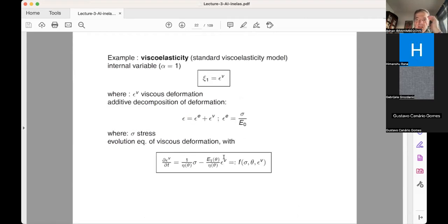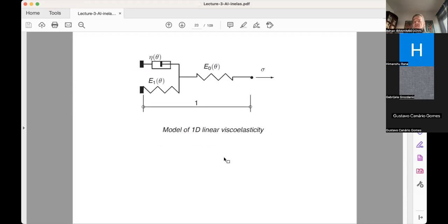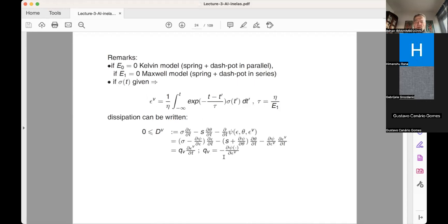We started studying that by looking into so-called rheological models that could be introduced by studying a simple one-dimensional problem, simplifying it to a unit-length bar with unit cross-section, in which case you can directly obtain the stress-strain diagram by studying the usual boundary problem. We started with linear viscosity to define a viscous deformation, which is the simplest model that you can introduce, but also not very usable for describing the behavior of real materials.